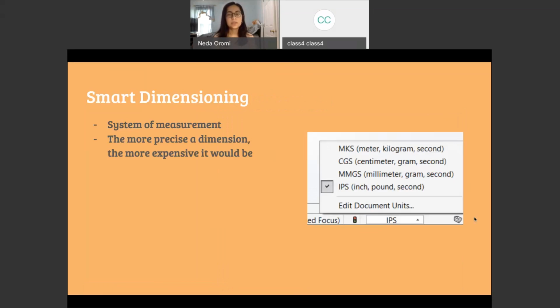Okay. Smart dimensioning. Like I mentioned multiple times before, it gives a measurement to your sketch. So you have to define every single part, every hole, every line, every curvature, because if you don't, maybe when you're CADing one time, you accidentally move something and you don't really realize. But later on, if you try to get that custom made, or you're looking at the CAD again, you realize that's not what I had made originally. And that's because you accidentally moved it because it wasn't fully defined. And that can create a lot of issues later on. So make sure you fully define everything.